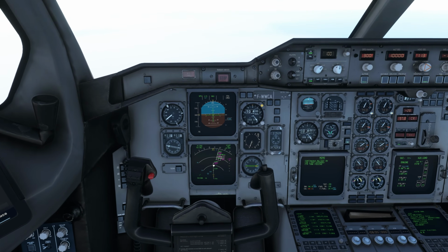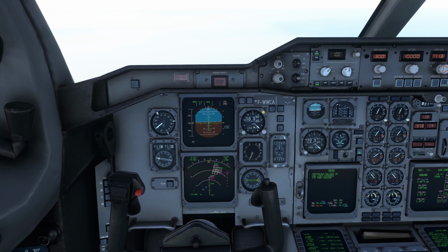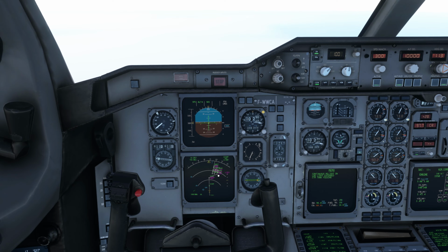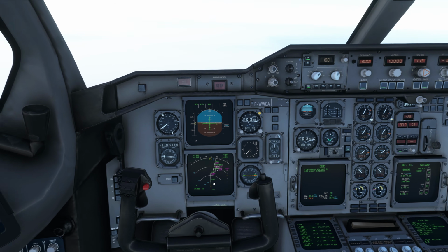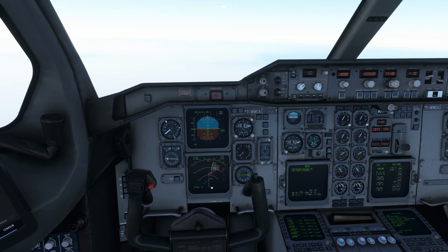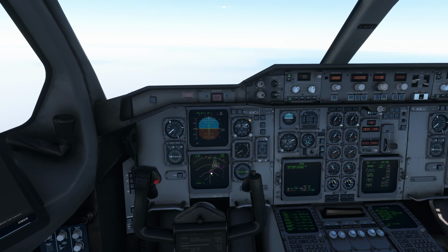Now you can see that the plane is going to be stabilized at 10,000 feet, and still there is some ground to cover, so it's good. And then at the next point, I should be at 7,000 or below. So after this point, I will start the descent further, and you can see the speed constraint coming, 230 knots, so I will further reduce the speed near this point.